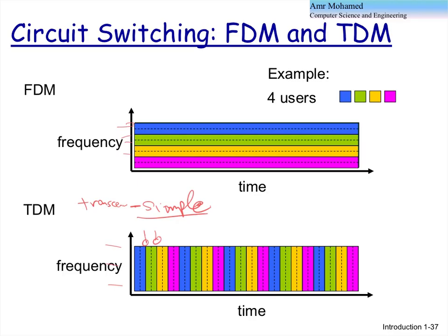If I ask you what time it is now with you, chances are I will find different times, right? Imagine these different users trying to synchronize their time slots. They are sending in their time slots, so definitely there might be some overlap. We call it time overlap, not interference in this case. So synchronization here is very key. In TDM, synchronization is an issue.